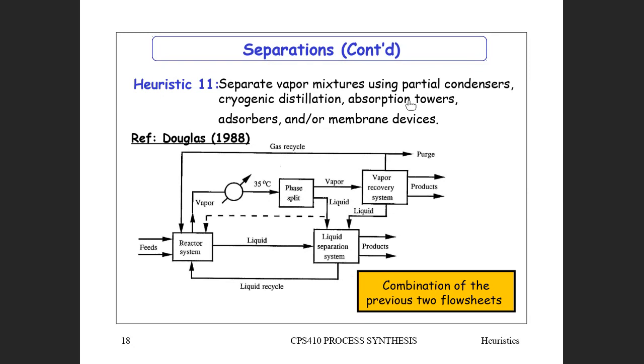And with synthesis gas, we will always have carbon dioxide and carbon monoxide and hydrogen. And carbon dioxide is pretty much a byproduct, and water. There's the water gas shift reaction, but water is easy to remove. I mean, you just cool down the gases using cooling water, and most of your water is going to condense out. But now, to separate CO2, CO, and hydrogen, what can you use?